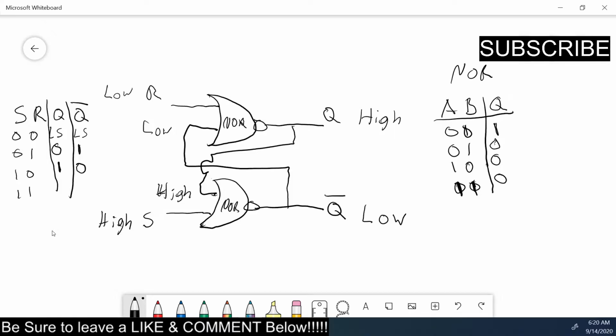And then if you press them both at the same time, you're going to get an unstable effect where they both go off and a random one will come on, and I'll show you that on the circuit. So you kind of don't want to feed in two highs to an SR latch. Now there are ways to prevent that with other gates, but we're going to start with the SR latch. So this is basically my horribly chicken scratched SR latch.